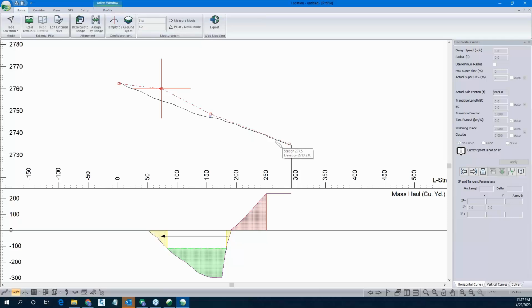We have an optimization module, and it's possible to define different vertical profiles, and these longitudinal profiles can be based on different parameters. If we want to have tangents between curves, it's possible to define them, and if for some longitudinal profiles we do not want any tangents, it's possible to define the profile just based on the existing curves. So we have 5 available options based on your standards and your design criteria. You can choose among these options.